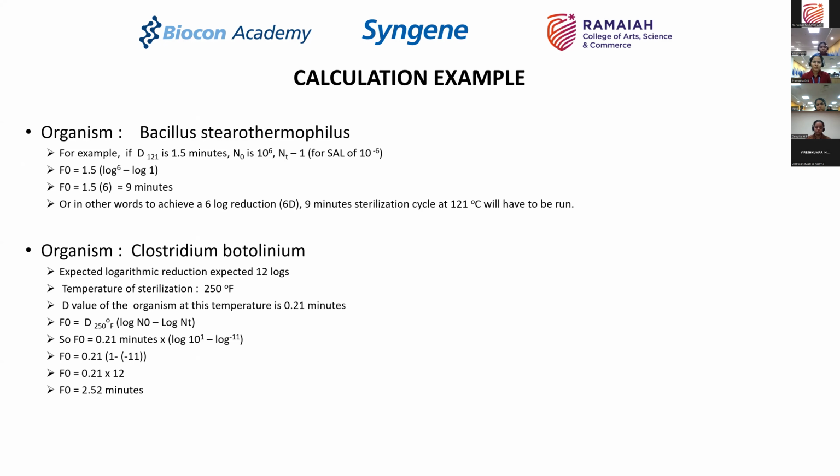for a given organism species, Bacillus thuringiensis being used as a standard organism if no other known tougher organism is available. Okay, so F0 calculation is done for every batch on an autoclave to make sure that your loads were running consistently. You cannot have one cycle.